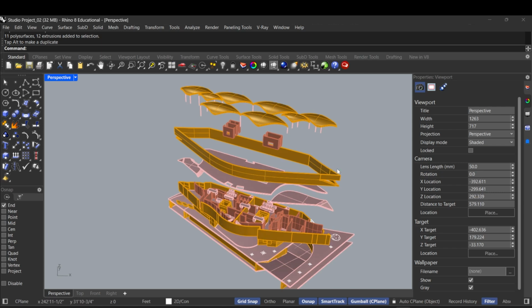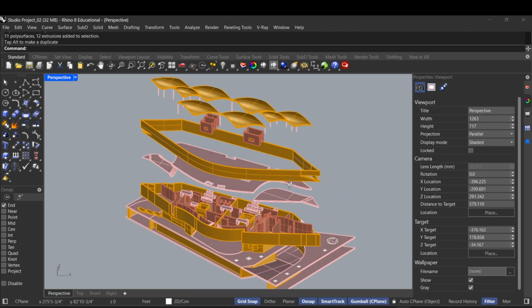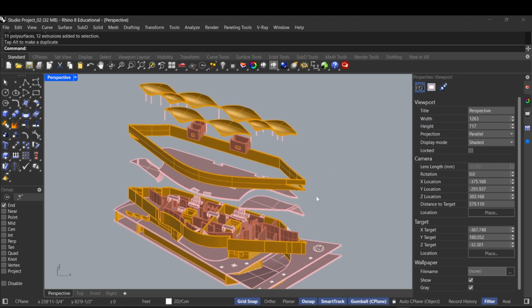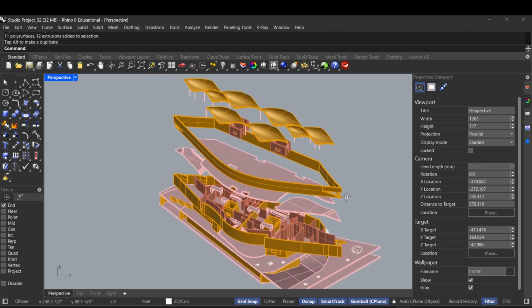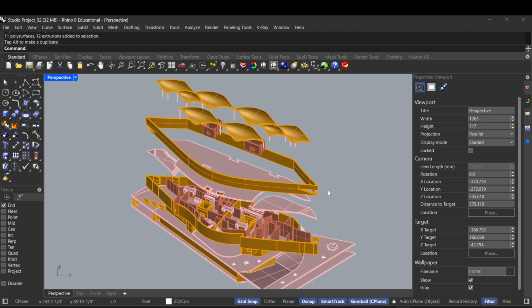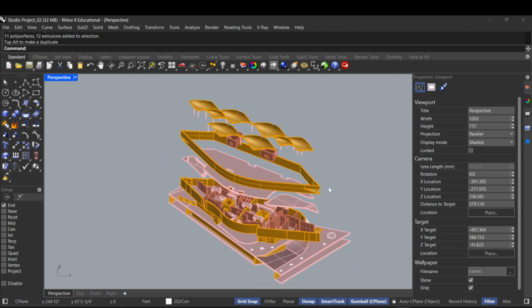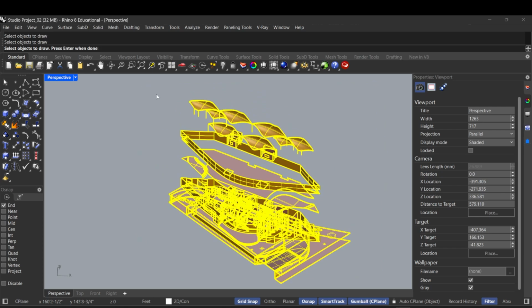And then the last part, again, one more time. So you need to get to the parallel view, set up your camera with the same axonometric view that you've been asked or you want to work on, and then make 2D, select all the geometries you want, and then you can actually focus on part of the project. But in this case, I'm just selecting all of it.